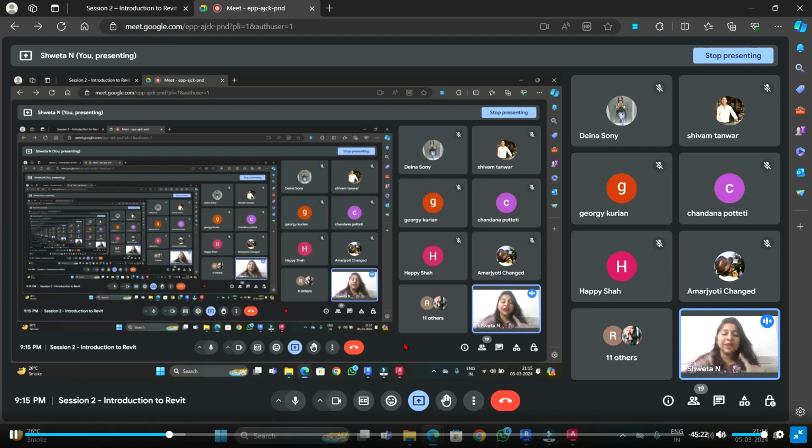If you change the height of the table from, let's say, 0.5 to 1 meters, automatically not only does your leg height rise, but the tabletop also shifts. So the whole table is adjusted. Whatever elements are associated with that specific parameter, what is a parameter? The property, let's say the height or the length, these are your parameters. Whatever other element is associated with that parameter also gets adjusted. That's known as a parametric family.